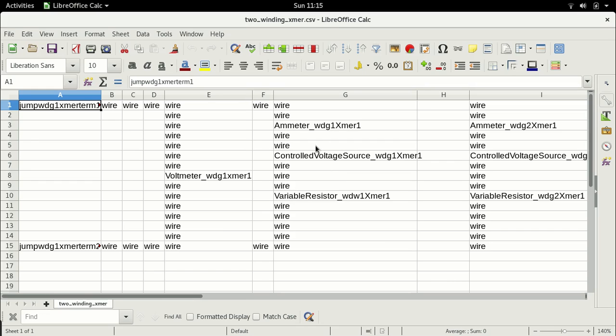Now, the way we have simulated, rather modeled this in these inductors, that is these two windings, is as a voltage source in series with the resistance, right? So all we are doing is we are calculating the current and we are adjusting our voltage source and our variable resistance so that we achieve a certain current, right? Now, the only problem with this is that we are doing all our loss modeling, everything in this one resistor,